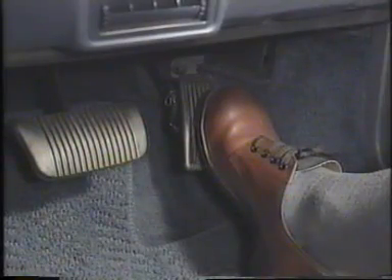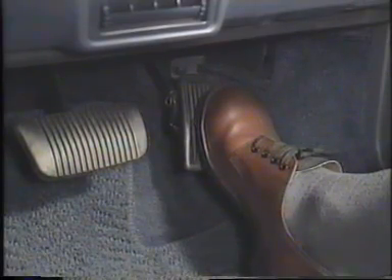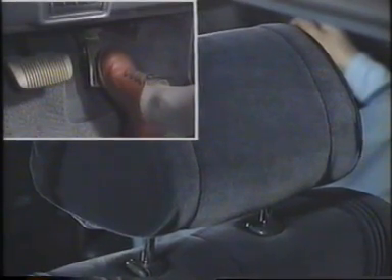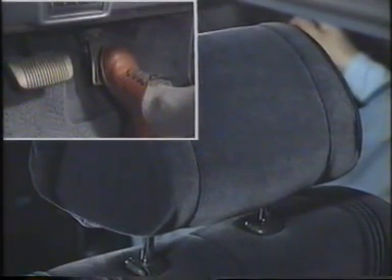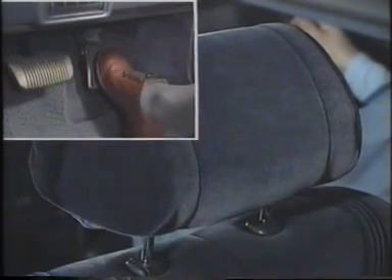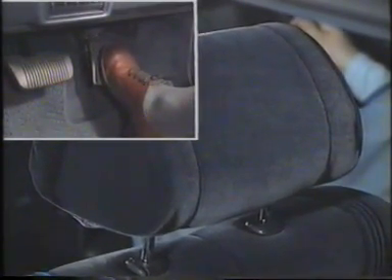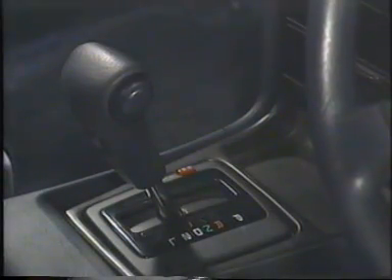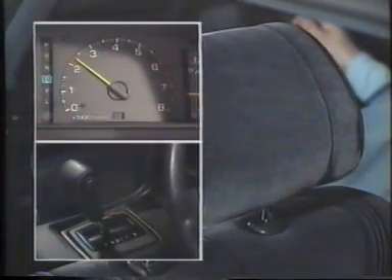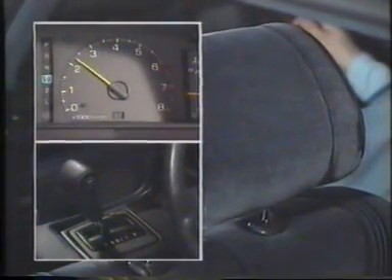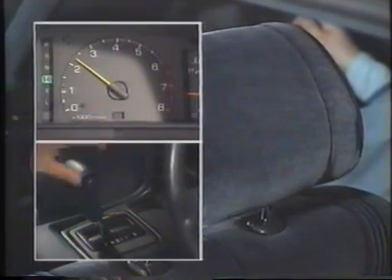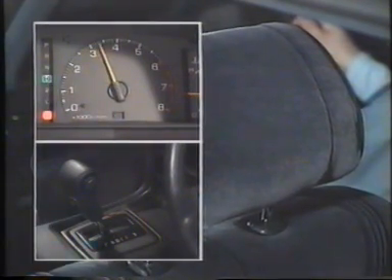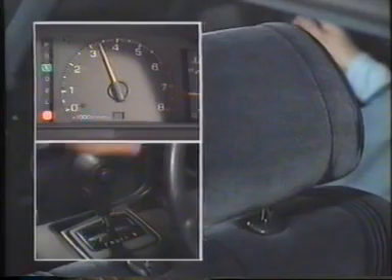You also need to know the relationship between the body shake and the engine load. You accelerate, cruise, and decelerate the car repeatedly, but the vibration seems to be unrelated to the engine load. The shift lever position and the engine speed often have effects on vibration. In this case, the shift lever position and the engine speed seem to be unrelated to the problem, as the vibration is still felt when you move the shift lever or change the engine speed.